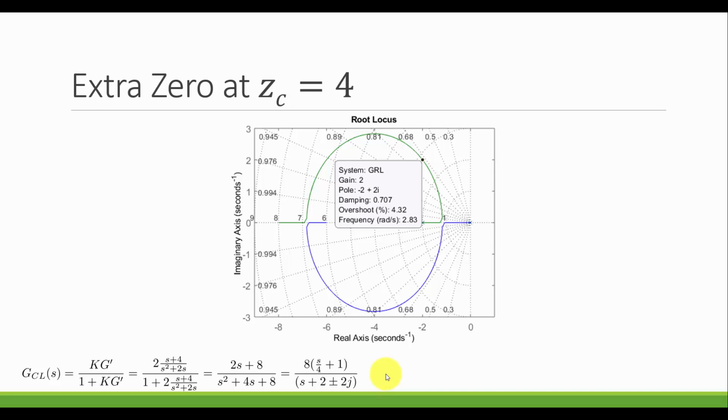So one thing we have to keep in mind with the root locus method is that when we're going through all the design process, when we're selecting our poles, we are treating the system as though the dominant poles entirely determine how the system is going to behave. It is not accounting for an extra 0, a third pole, a fourth pole even, one or two zeros that we're adding into the system. And we know that those modified systems are not going to act exactly like the second order baseline system that we usually are looking at.